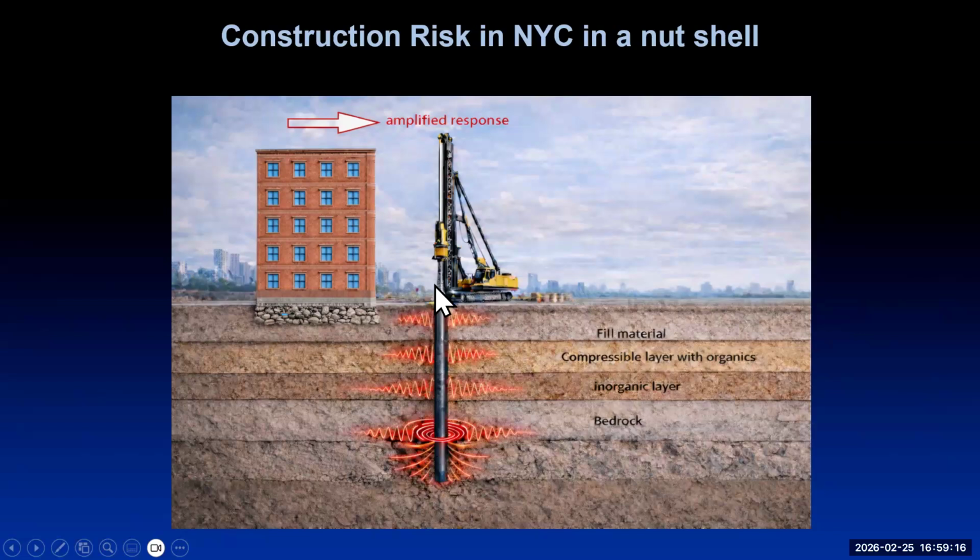And they will, especially if you get down to bedrock, and some of these are on piles. Now you have a transmission of energy into the structure. And what happens when you're pile driving, when you're drilling, or when even you're excavating, these different layers can cause the amplification of response in the building. And here's the crazy thing. The standard methods for monitoring are at ground level. Well, you'll never pick up amplification and you'll never understand if vertically the building is moving.